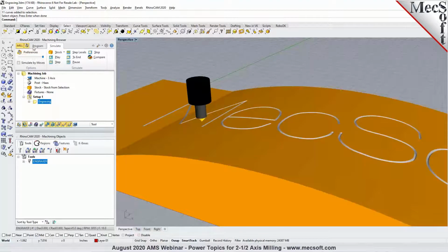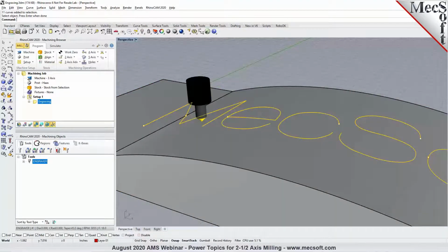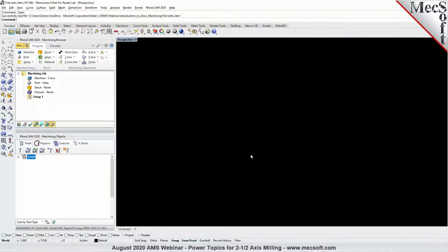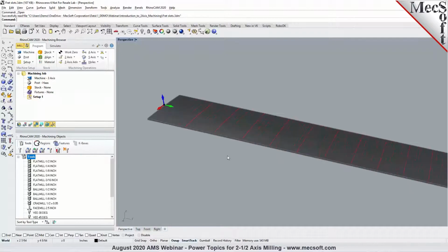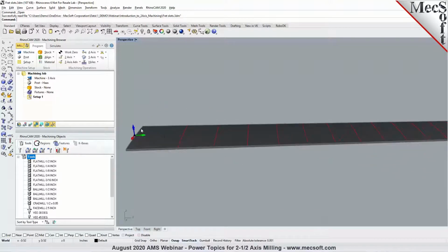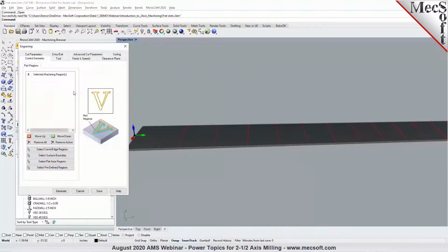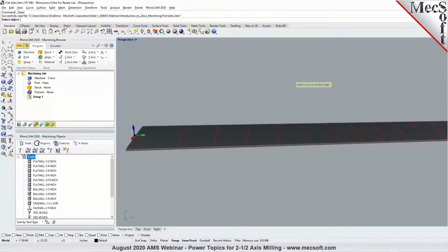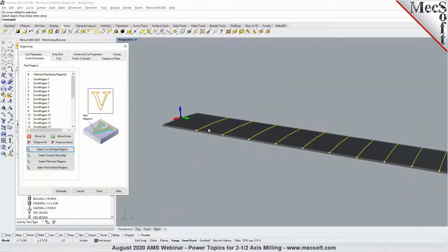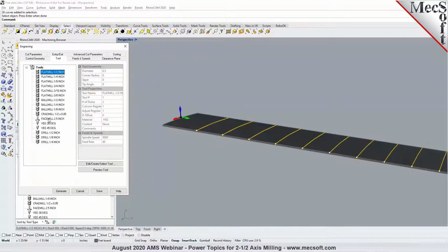Now, a lot of our instrument makers use engraving for machining their fret slots. You don't have to model the fret slots in your CAD. Instead, you could just create those three-dimensional curves or the arcs from either the XZ plane or the YZ plane, and use 2-axis in engraving, and just select those curves as your control geometry or the drive geometry, and then pick a tool for it.